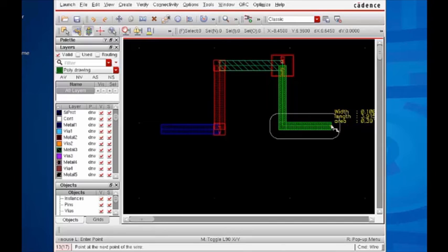And then we can see the differences as we move through. So that's wire editing, and it's also path stitching. So we were afforded the benefit of having the vias provided for us. So you can do an enter to finish that, or a double click.